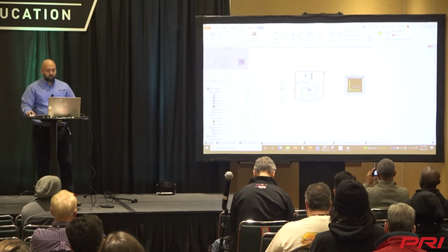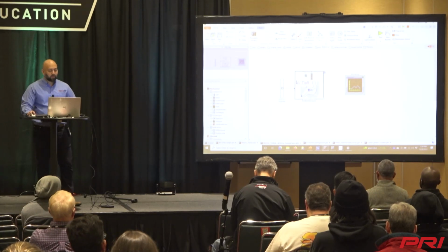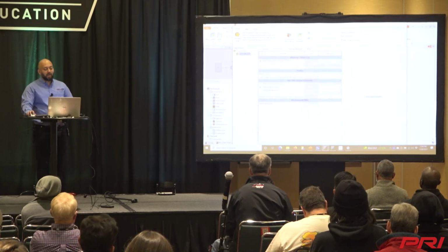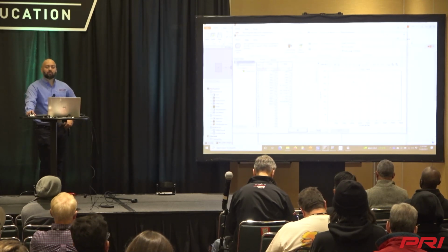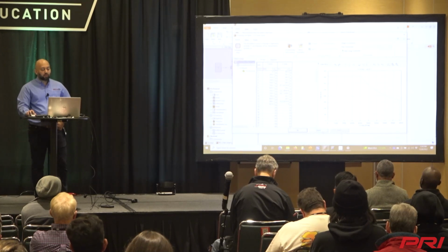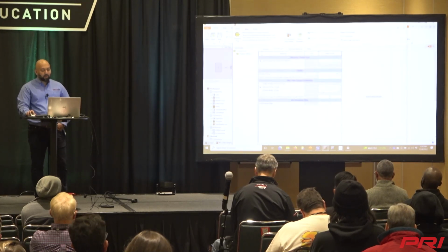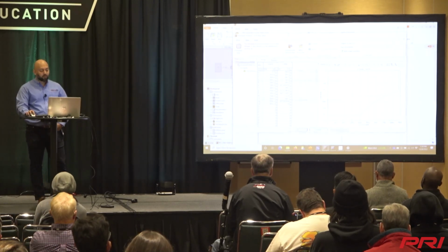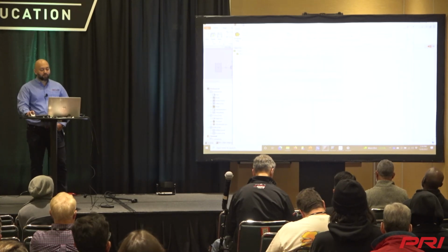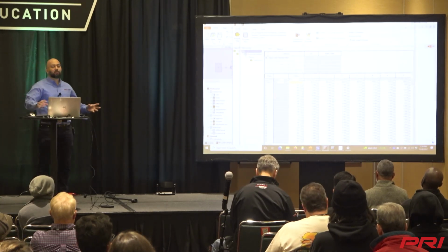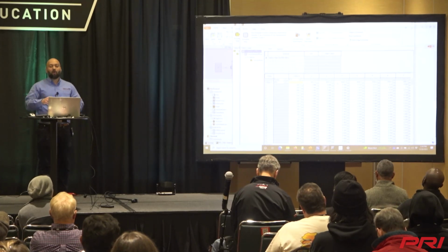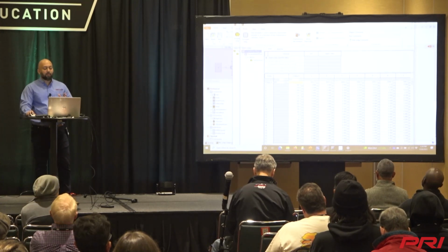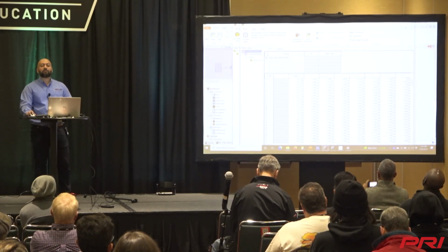The first thing that gives power to the wheels is going to be the motor. Here we have a map-based motor which has a maximum torque on the depletion side and a minimum torque which is used on the generation side when braking. Then you have a motor efficiency map, which is like XYZ data. You can think of it like an island, with motor speed on the x-axis, motor torque on the y-axis, and then different efficiency numbers.